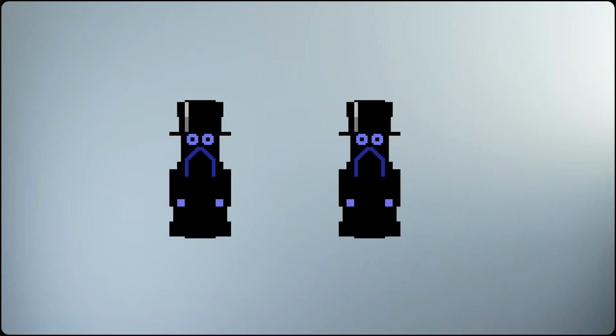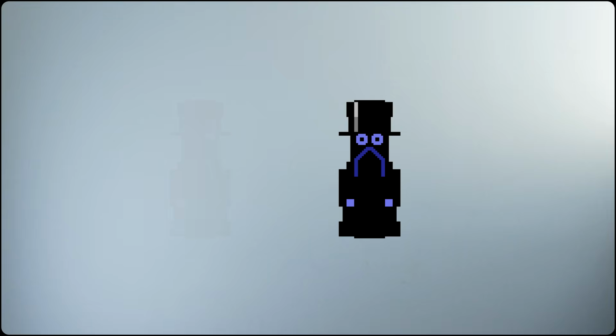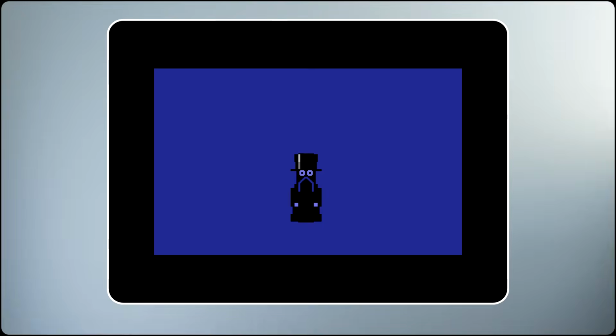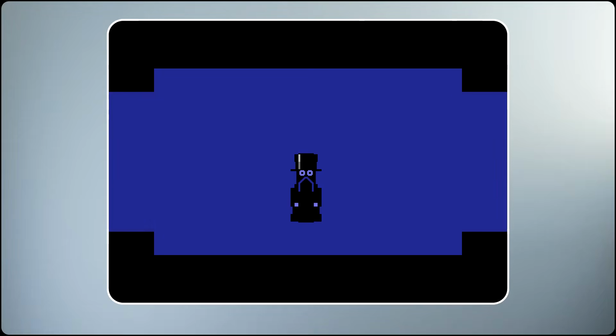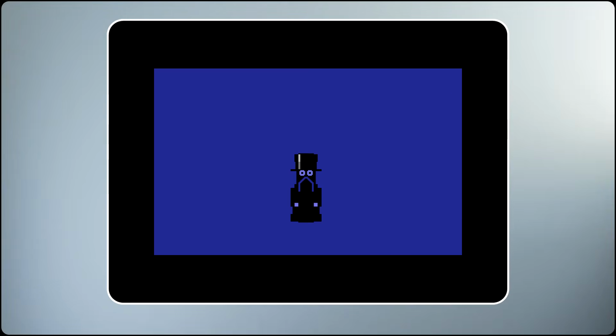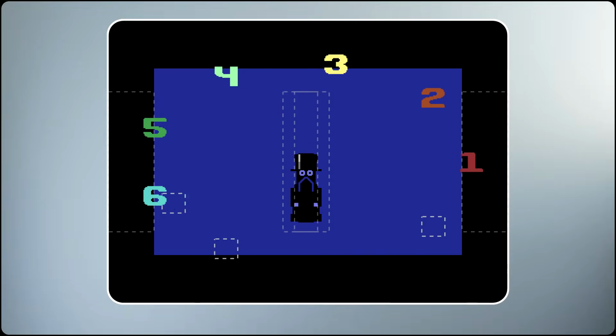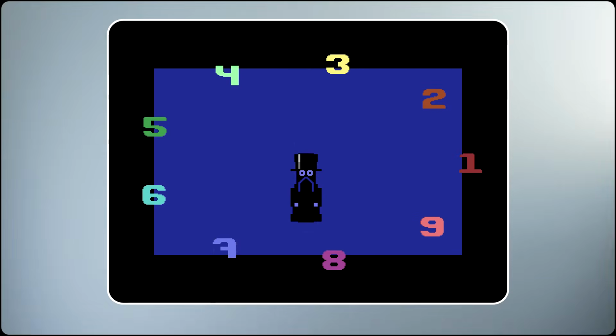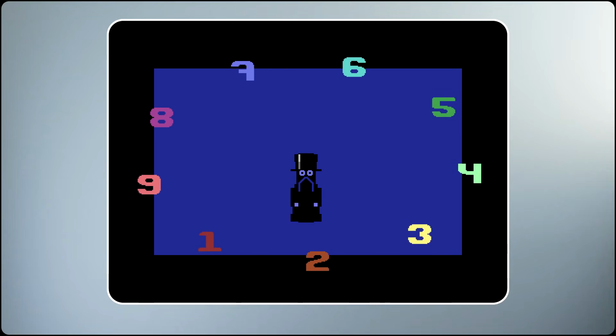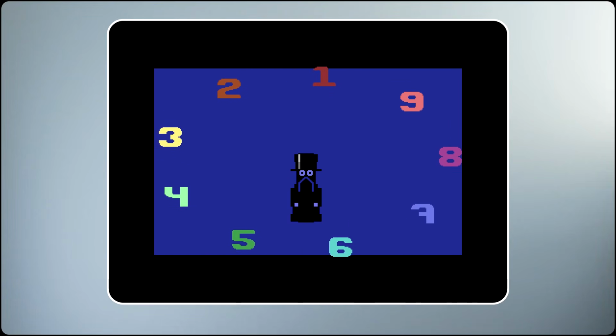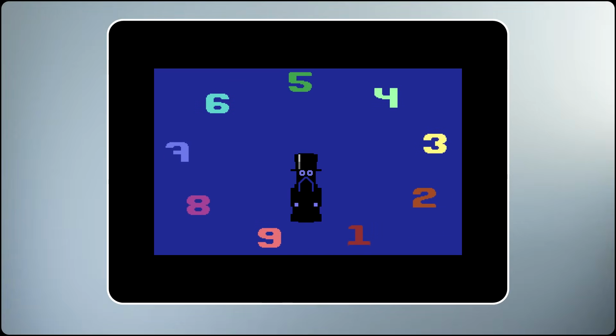Again, I won't go into the specifics of why this is helpful, except to say that it simplifies the timing, which in turn lets me open the side borders in this part of the screen. That exposes the blue background color, so 2 vertical stacks of solid black X-expanded sprites are needed as a cover. Together, these 4 static sprite columns help to stabilize the DMA timing of 3 freely moving sprites that are used for the actual multiplexing. And 3 physical sprites is enough to cover the 9 digits when the circle is this wide and sparse, but as the circle shrinks, I have to seamlessly switch back to regular multiplexing.